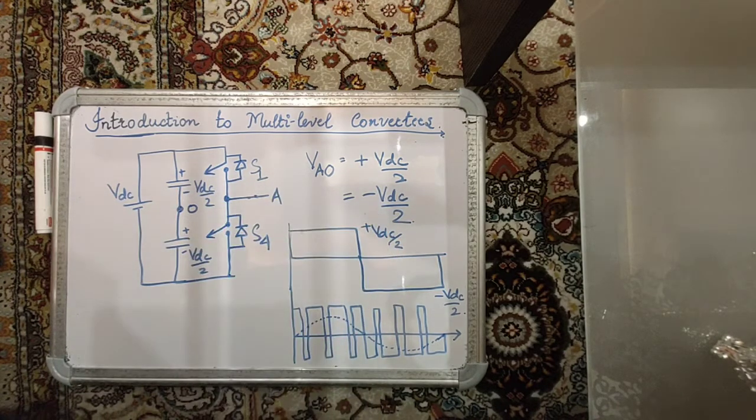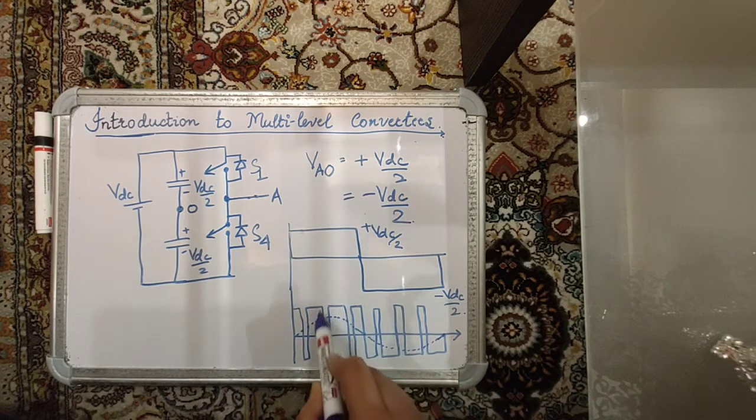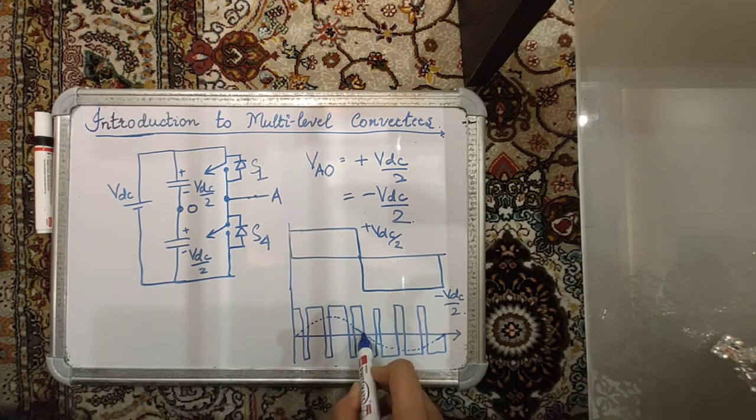This is done in such a way that the sampling gives you a sinusoidal representation, or you can say that the instantaneous averages of this output voltage waveform is a sine wave. So you have a fundamental component at your required frequency, say 50 Hertz.